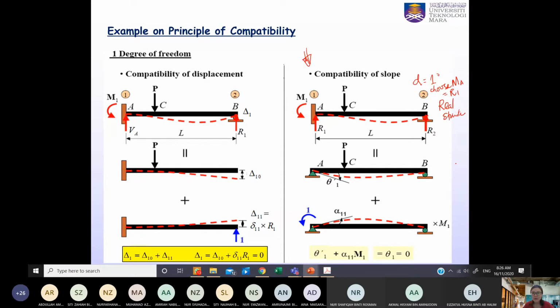For this node, you can see that this fixed support has changed to a pin support, meaning that the moment has been taken out. But for those who are not sure, when the moment is taken out, what happens? Does the fixed support become a roller or a pin? If you keep getting confused about that, don't draw the supports. Just draw in terms of forces, the support reactions.